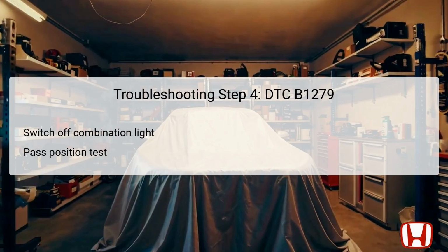Wait at least 6 seconds after switching to pass position. This time allows the vehicle systems to stabilize and register the changes correctly. Observing the lights during this process ensures that they behave as expected without flickering or failure. This step is critical for diagnosing possible intermittent issues that may arise only under certain switch positions.